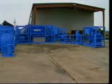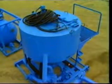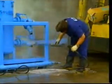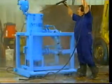The surface equipment required for the operation generally includes blenders, triplex pumps, and filtration equipment. All surface equipment must be clean. No rust, sludge, or debris should be on any part of the equipment that may contact the treating fluid and contaminate the gravel packing fluid.